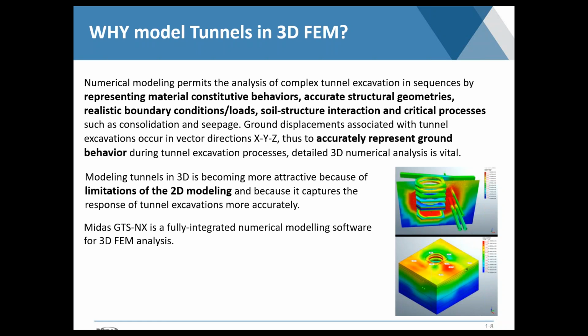And the session today is to clarify why tunnels in particular should be modeled in 3D FEM, or finite element method in 3D. So as we've seen, we could do some tunnels by just simplifying it, giving a spring and giving it some sort of stiffness approximation, but it's not really going to capture the behavior of the ground. That is more appropriately captured by what is known in the field as constitutive materials or constitutive theories.